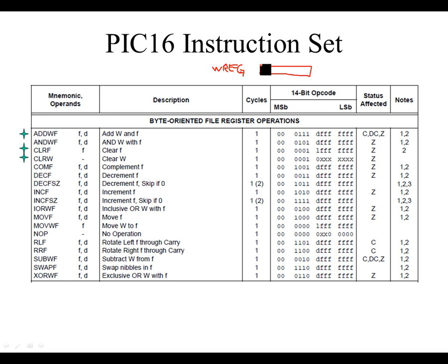It's what we talked about before. It shows you the ALU, so the result can either go into the W register or the F register, and the result comes from one side of the addition legs of the ALU. If you look at how the ALU is designed, it always comes from the W register, and then it can go to the W register. So it's important that we have control over that one as well. In this case, it's just going to allow us to clear the W register.